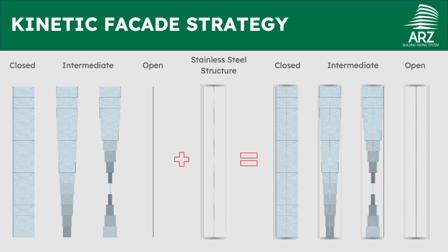Each rectangular piece can rotate 360 degrees autonomously without affecting the rest of the rectangular pieces, thus reducing the direct sunlight penetration in July and April when needed. However, during the winter, direct sunlight penetration is needed to achieve passive solar heating, and so the kinetic facade responds to this information by staying rotated at exactly 90 degrees, allowing the low winter sun to penetrate into the space.